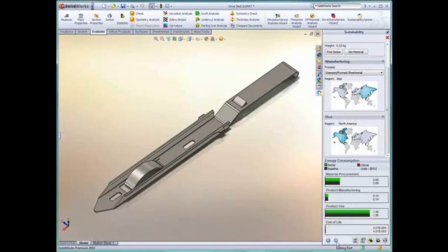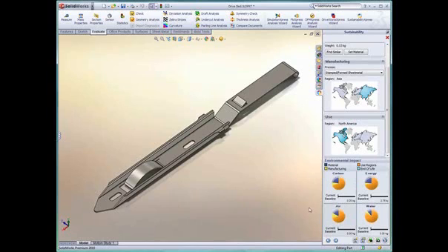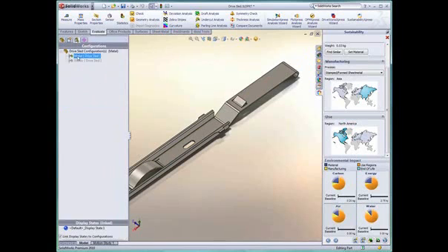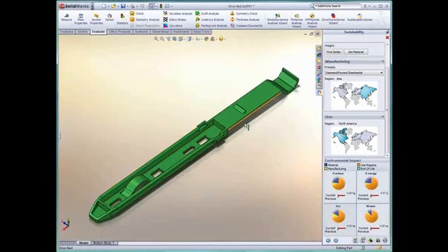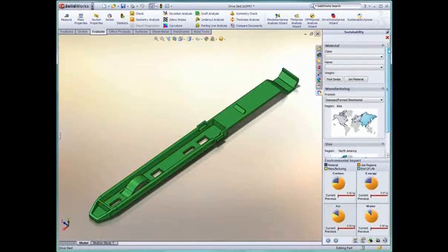Let's say we set this design as our baseline and would like to compare it with another design to decide if it is possible to make meaningful changes. Here we are looking at a plastic dry slab. Again, I will define its material, and in this case it will be plastic, let's say ABS-PC.